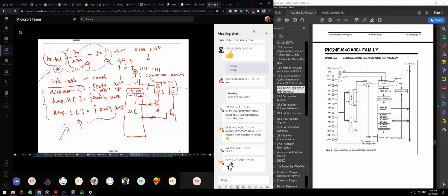If you don't want this, then you change the 74244. 74244 is just a buffer to give enough current to drive all these 7 segments. You can change this to a BCD 7 segment decoder. If you're using a 7 segment decoder, you don't need all 8 lines here, correct? I think it's 4 lines only, correct? So it's up to you how you design your system.